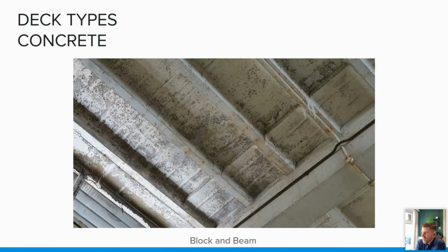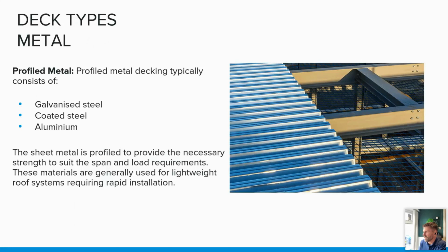So moving on to the last one used in modern construction, I should say, which is a metal deck. These are usually used for speed and lightweight, usually in conjunction with a mechanically fixed system, and the most common one of those is a single ply. So when you're looking from the underside, it's not uncommon to see fixings protruding through these metal decks.